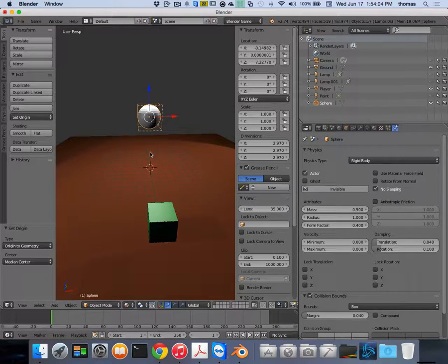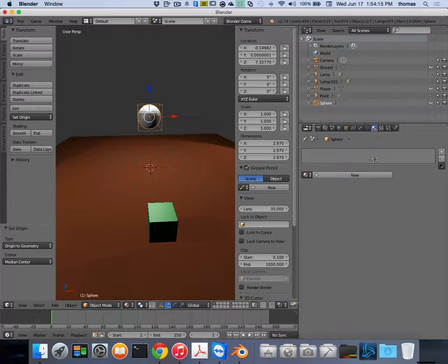Here's the other reason why it's not moving. Do you see that there's a material applied to this thing? The answer is no. No material, no physics. Let's try this out. So I'm going to go to the material, add a new material, or I